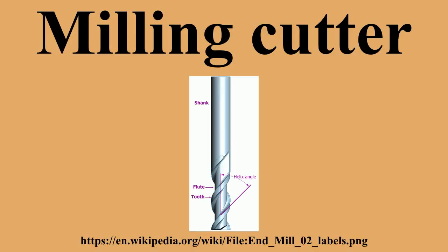Fly cutter. A fly cutter is composed of a body into which 1 or 2 tool bits are inserted. As the entire unit rotates, the tool bits take broad, shallow facing cuts. Fly cutters are analogous to face mills in that the purpose is face milling and their individual cutters are replaceable. Face mills are more ideal in various respects, but tend to be expensive, whereas fly cutters are very inexpensive.